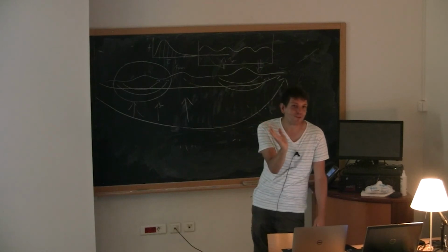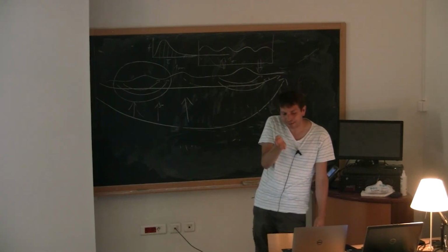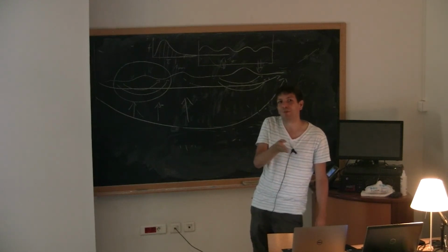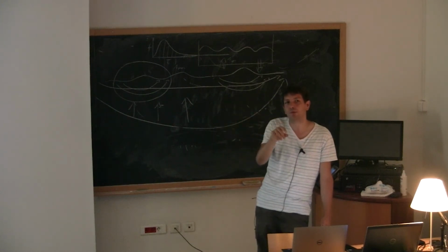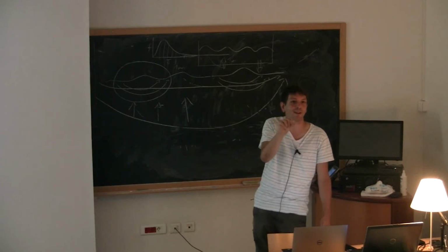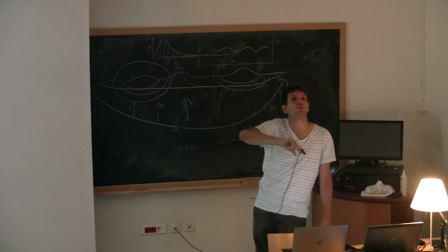This value actually applies very close to the wall, so let's say at the nanoscale. Which means that if you can grid your geometry up to a few nanometers, so you have some grid blocks that are a few nanometers, you can apply this contact angle and it will work.